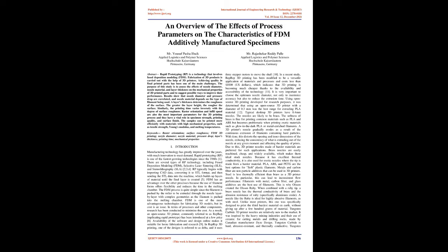Similarly, the printing time varies inversely with the degree of surface roughness. Raster orientation and infill speed are also the most important parameters for the 3D printing process, and they have a vital role in specimen strength, printing quality, and surface finish. The samples can be printed more efficiently with materials with high mechanical properties, such as tensile strength, Young's modulus, and melting temperatures. Keywords: raster orientation, surface roughness, FDM 3D printing, nozzle diameter, nozzle material, pressure drop, layers thickness, printing time,